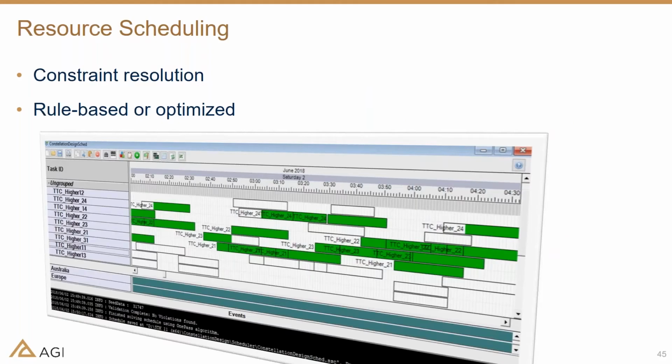One of the other simplifying assumptions early on in our high-level system trade study was that comms were fully available and that there were no resource constraints that would in any way impede the execution of the missions that we were looking at. So one of the things we might want to do is to look at the accessibility to ground stations for telemetry and commanding communications and actually run a schedule that is able to pull out any resource conflict and resource constraints. And that's what we've done here.